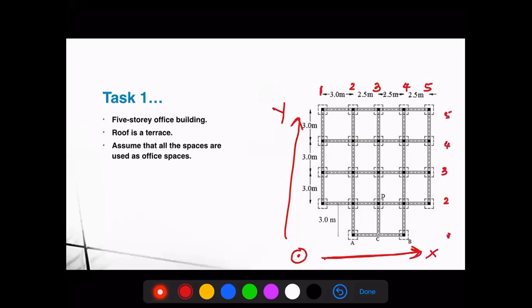Right? Number of grids in Z direction: what we normally do is we model one floor and we copy it. In SAP we call it replicating, not copying. Copying is there too, but it's for a different thing. So if you want to create a floor and copy it to other floors, that's called replicating.